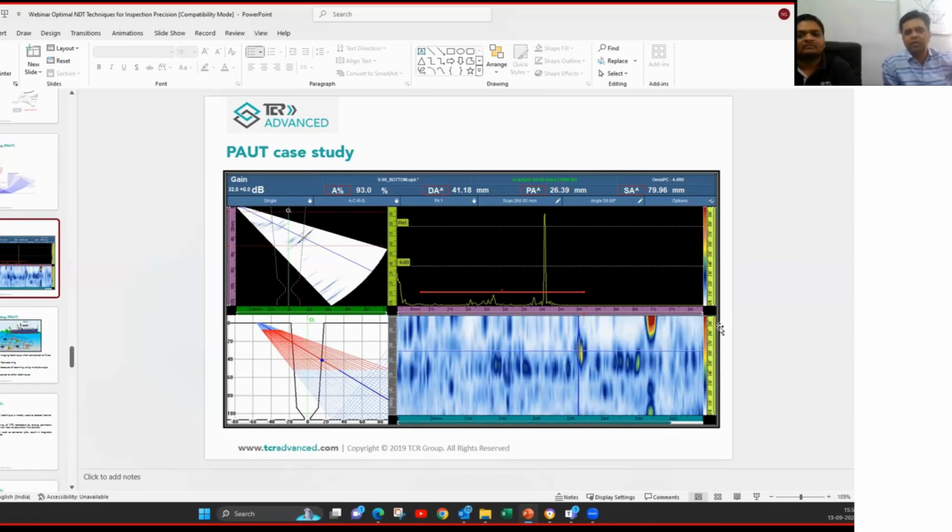But we cannot detect cracks in conventional eddy current testing. If it is array eddy current, there are certain high sensitivities involved, and we can detect that. So going with ECT, the correctness is not a question. There are certain limitations where you cannot detect less than 10% of the volume which is being checked.